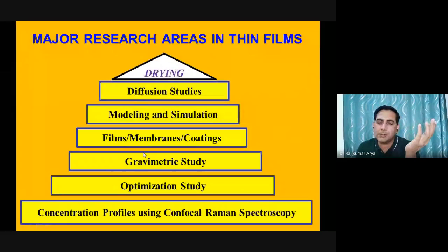All your plant materials, plant reactors, your vessels, your distillation column, you are not supposed to weigh them because the weight is very high and the coating material is very low. So you cannot identify anything in that particular case. In that case, gravimetric study is not allowed. You can do only depth profiling by concentration. You just take some particular point, do the depth profiling at that point, and see how my coating properties are there, composition, and all this.